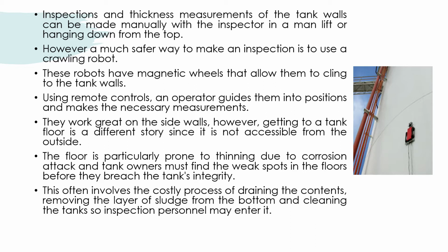However, getting to a tank floor is a different story since it is not accessible from the outside. The floor is particularly prone to thinning due to corrosion attack, and tank owners must find the weak spot in the floor before it breaches the tank's integrity.